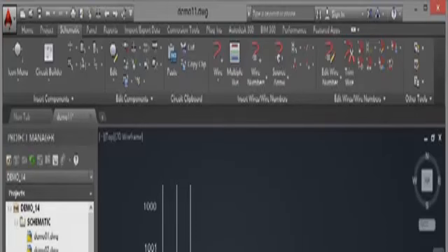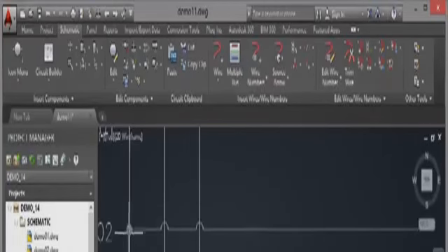There's my wires, and the lovely thing is when I press enter now and I zoom in here, you can see, look, I've got a connector on each of the wires, and I've also got my wire gap loops going across the wires where the wires go across. So that's how I can place my three-phase ladders and my multiple phase wiring in my AutoCAD electrical drawings.